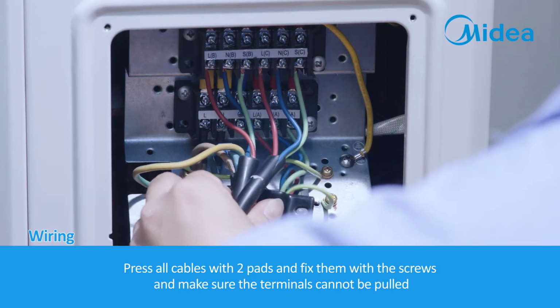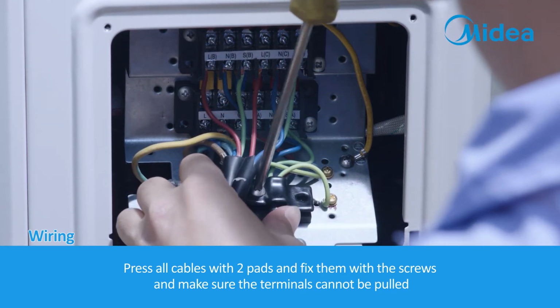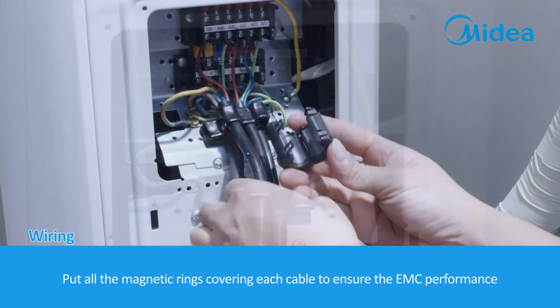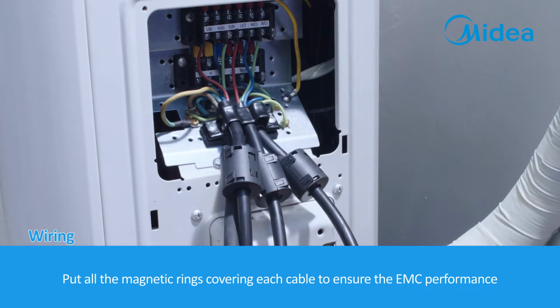Press all cables with 2 pads and fix them with the screws and make sure the terminals cannot be pulled. Put all the magnetic rings covering each cable to ensure the EMC performance.